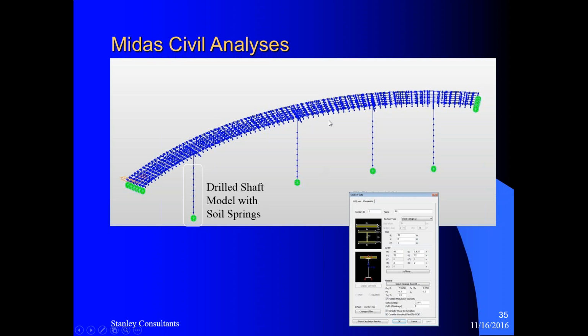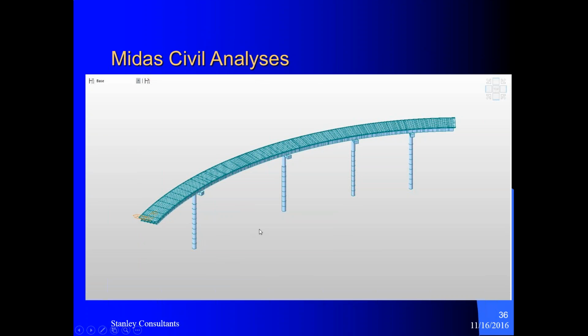So when you define the girder element here, click that consider warping effect box. That way you will get a better representation of the warping stiffness of the system. And this is how the model looks.